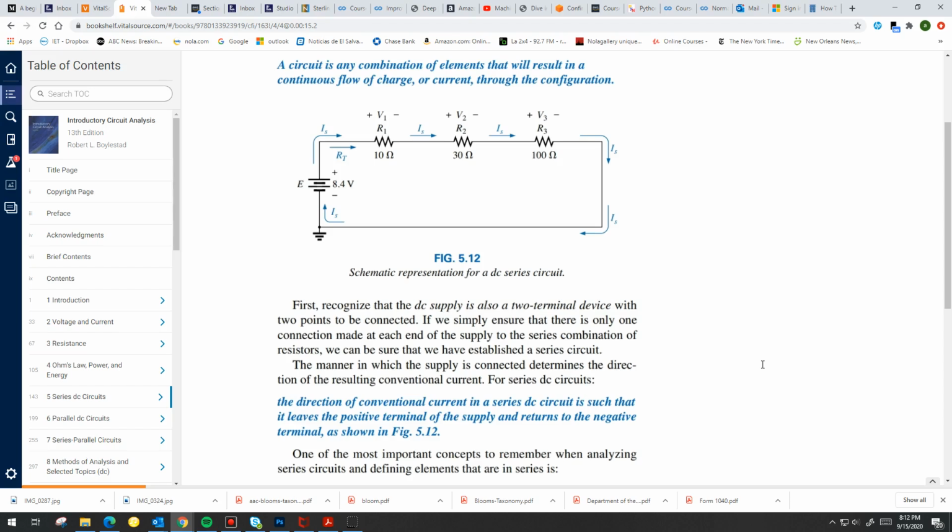However, if you're told that the current is the same through some of those resistors, it doesn't mean they are automatically connected in series. It goes one way but not the other. If you already know ahead of time that the elements are connected in series, then by default the currents will be the same. But not the other way back. All right.